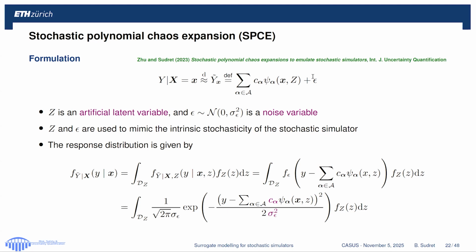So if you have many parameters, some of the x's you put in the z, and then you're back to the small case. You probably need some prior, simple sensitivity analysis to focus on a small number, up to 10 x's. If you have many more than that, then you should reduce somehow, which does not cover all problems, but in many problems with many parameters, if you look carefully, you just have a handful that is really important. So that's how I would handle this.